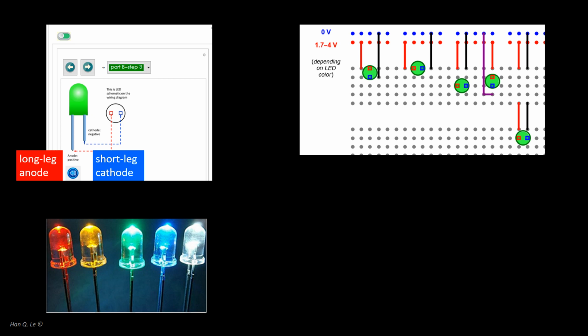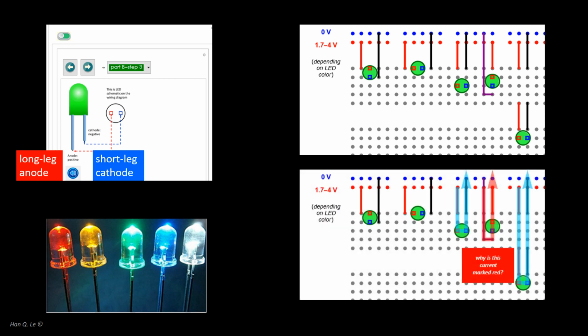By removing just one wire, you will see that the power supply will no longer be shorted, and some LEDs will emit light. After the above mental exercise, by visualizing in the mind the current flow, you can choose an LED wiring configuration that works, one with a light blue arrow as shown, for measurements. Follow the same suggestions as in the single resistor circuit above, such as using a jumper wire to open the circuit and insert the current measurement probes.